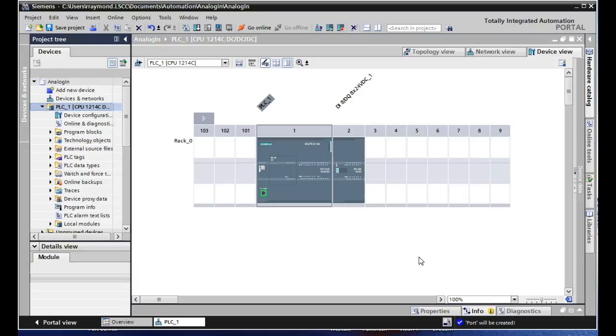So what the ADC does, we have different things. We can go to single bit A to D converters, which we see on a lot of our sensors over there, right? You understand? Where the sensing element itself is an analog sensor, but yet inside, the electronics that run the sensor convert that analog over to a digital. So what we do is most of them give us the ability to set what we call a threshold. So we can set when the sensor switches from a 1 to a 0 or vice versa.